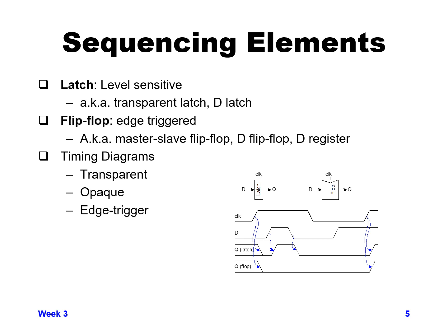Now, as we follow the waveforms along, D switches back from low to high. The latch will follow that D value going from low to high, and also follow it going from high to low, because clock is still high. As long as clock is high, the output Q of the latch will follow the value of D, and so it will switch. On the other hand, the flop stays low the entire time because it only captures the value at the instant when clock went from low to high. So it ignores the value of D all other times.